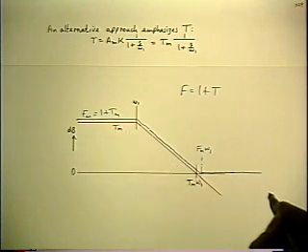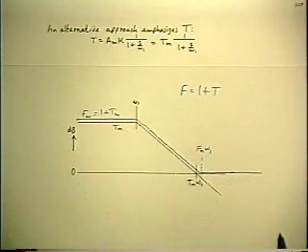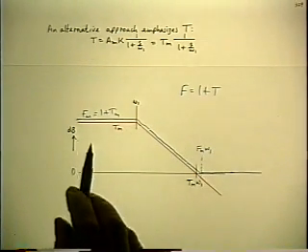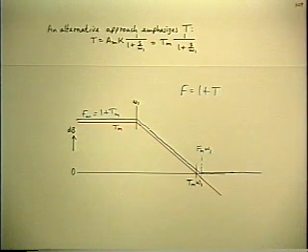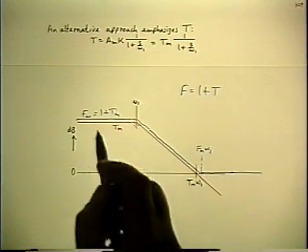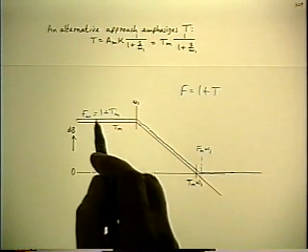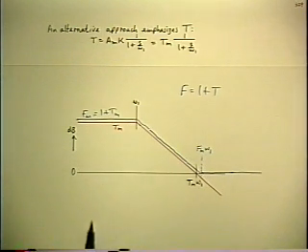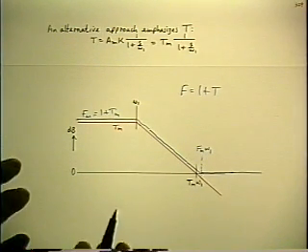We have two flat gains. You can choose either one as reference, depending on whether you want the answer to have the zero frequency flat gain as reference or the infinite frequency flat gain as reference. The choice is obvious this time, because the interesting part of the problem is at low frequencies where you have a lot of feedback, so that's clearly the one that you'd want to adopt as reference.